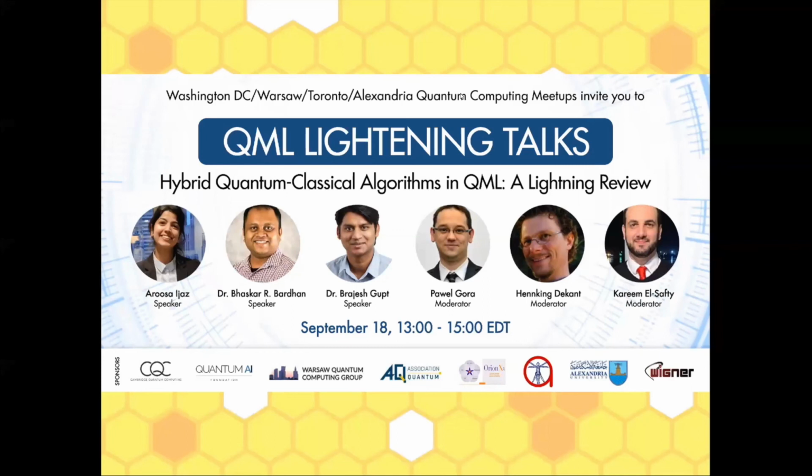And we all know these inverted Christmas tree pictures of the way that these superconducting chips are kept in their cold storage. So you have all these elaborate steps. As they go down this Christmas tree layer by layer, they get colder, and you are stripping out noise from the cables that connect the outside world to the quantum chip. So it's really quite elaborate to get the data in and out, just from an engineering feat. From a practical standpoint, I think that is going to hamper the hybrid model.